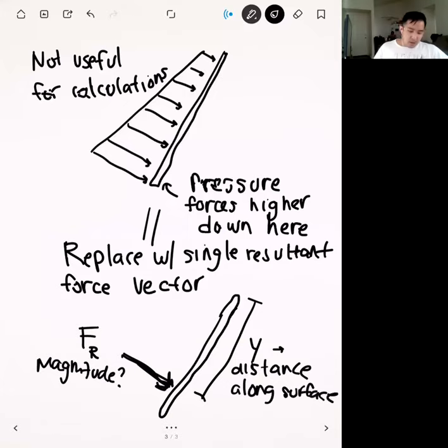Okay. So usually, I think the most difficult thing about these types of hydrostatic force problems is imagining the geometry. So oftentimes, especially if you have an inclined surface, you have to deal a little bit with trigonometry. You also have to have a little bit of imagination too, because oftentimes when we view these surfaces, we're viewing just the side profile of it. But you have to kind of, in your mind, turn the surface like this and tell yourself that there's also a full surface over there.